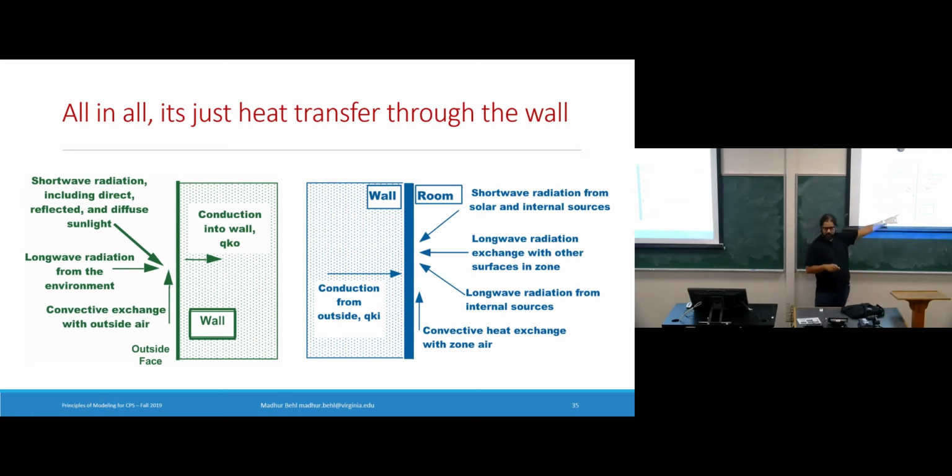That's not the only thing which changes the inside temperature. The conduction will change the inside temperature. The occupants are also emitting radiative energy, which we just saw. So there's a radiative exchange which is also getting absorbed by each and every surface of this room. So there's like a trigger from both sides which is governing the outside and inside temperature of the wall. But that's the understanding that we need to have. So going to the actual model, and then I'll pause for some questions because this is new stuff now.